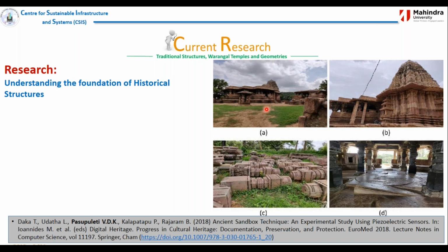Since it is confined, the soil has to be confined, it should not be open. If it is open, a lot of liquefaction can happen. This is what the Taj Mahal might face in the future, because it is on the Ganga river, and Delhi is an earthquake-prone area. If there is an earthquake and the soil is not confined, then it will actually undergo the liquefaction process. Water comes into the top and it loses strength.